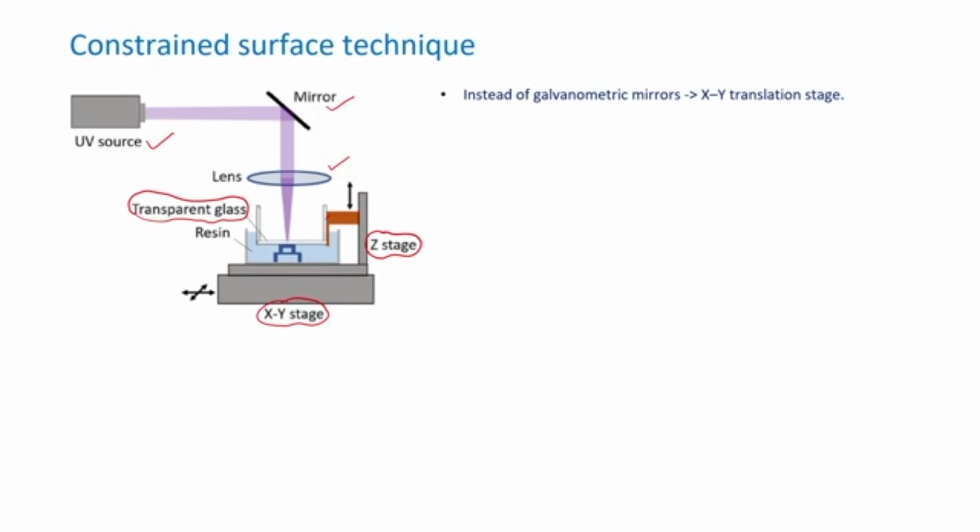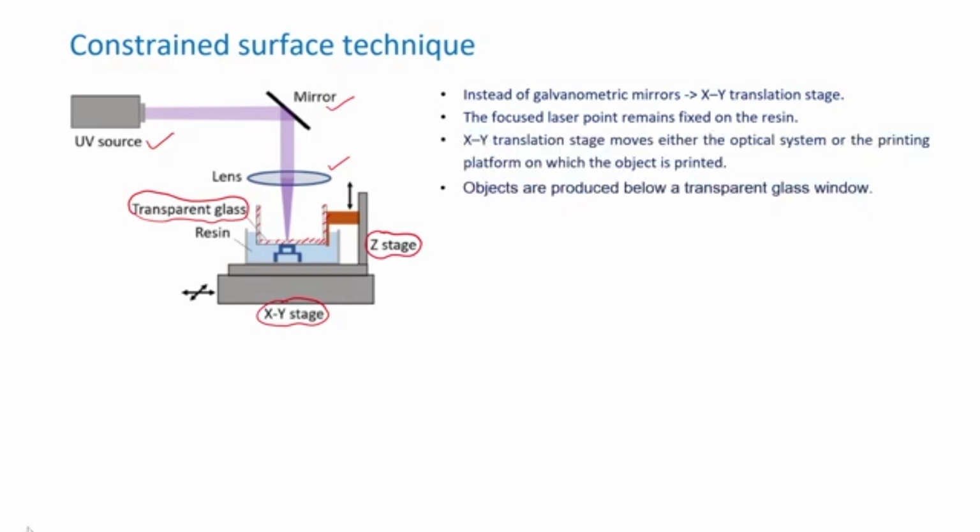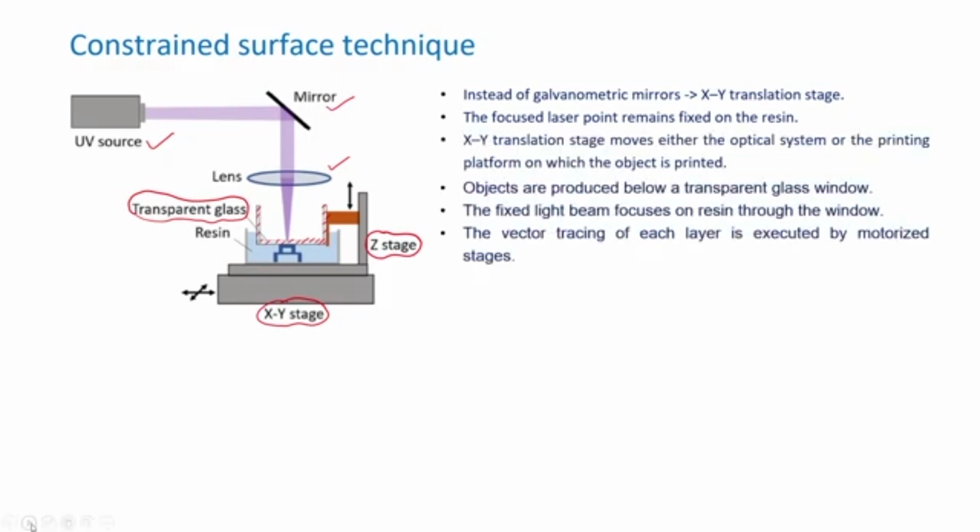But you notice here we are using a transparent glass, and this transparent glass allows a uniform pressure to be applied on the surface. When curing is occurring, to have uniform curing, and so that there is no spilling of the liquid resin over the cured surface immediately, a transparent glass arrangement has been used. So, here the same things are noted.